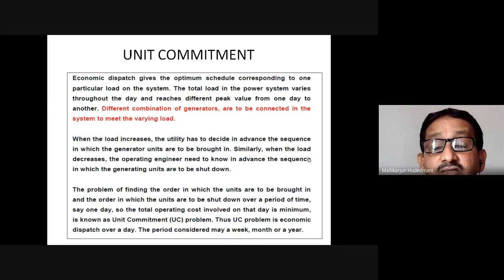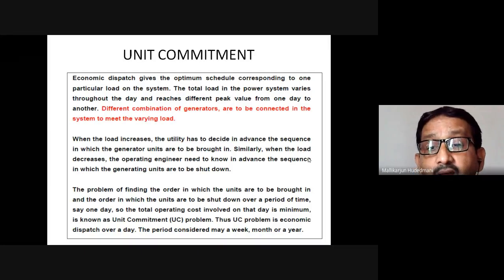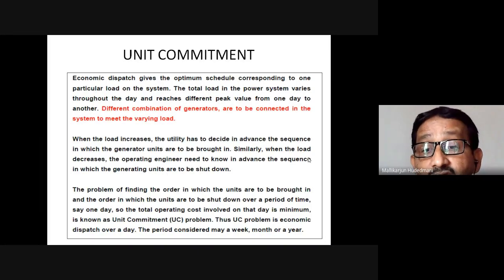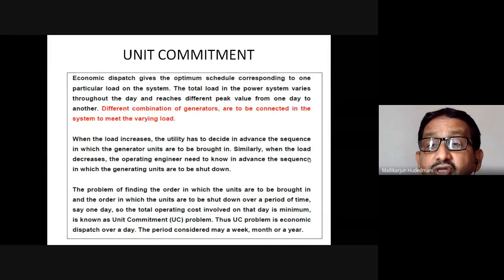Unit commitment is a schedule: commitment from the selected generators of a certain generating plant to meet the changing requirement of the plant, so that those identified generators are capable of taking the dynamic changes of the load and able to provide the megawatt as required in a very cost effective manner over the minimum to the maximum capacity of their combination.